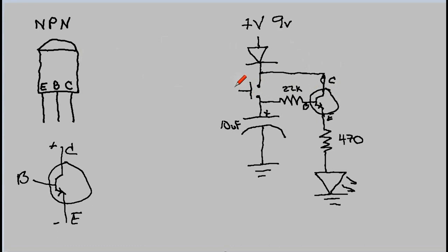When we physically put our thumb on this switch here and press this down, we then supply juice to the electrolytic capacitor. It fills up the electrolytic capacitor and it pushes against this switch. When that pushes against that switch, current now flows down through this resistor, through the LED to ground. And I should have done a little line before ground, but that's okay. And then that lights up.